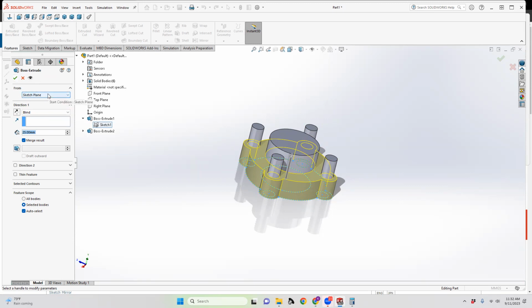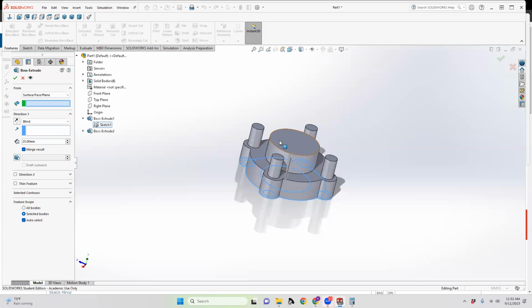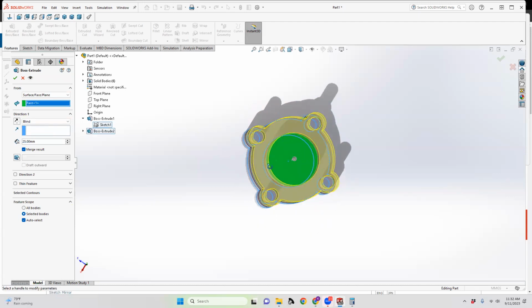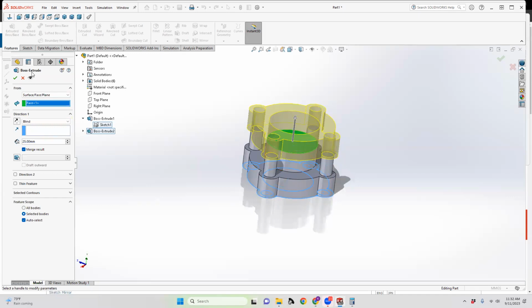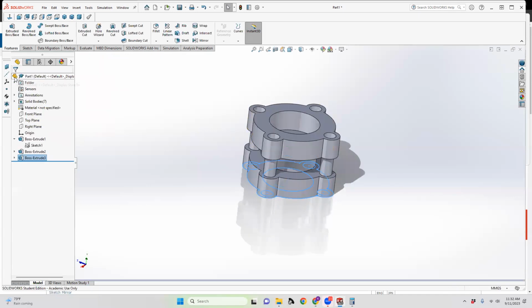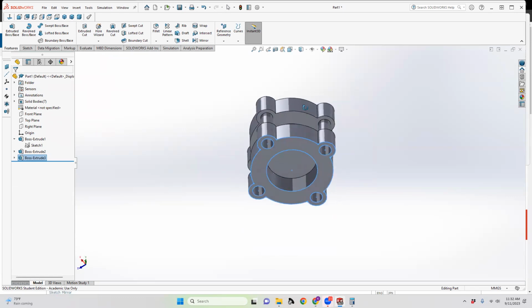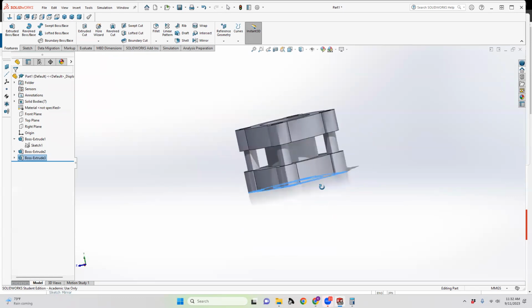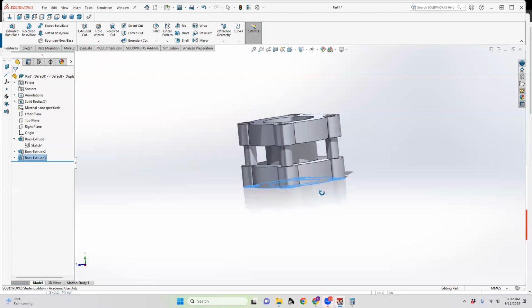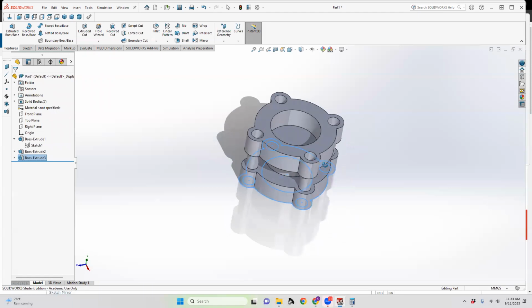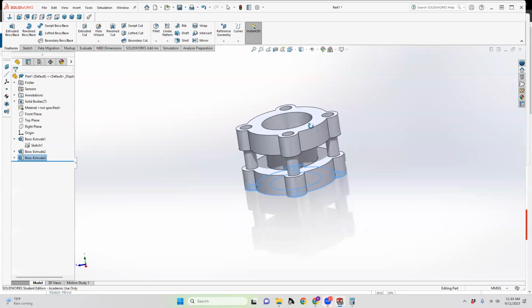So from the sketch plane, instead, you're going to do from the surface again. And in this case, it's selected the correct sketch region so that we can go back and forth. And so what that does is that allows you to now create a reasonably complicated part. And we've only used really, truly a couple of the sketch features, and we've already created something pretty cool. So the idea here is to think in terms of each of the dimensions as you're going up.